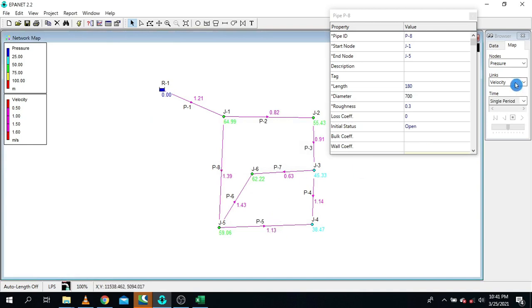At least now, okay, unit head losses, both of them are below 10 meter per kilometer. You can see here is 0.8, 0.7. Again, this one is 2, this is 3, 4, 10. Not bad. So at least now our system is well balanced. Velocity is within acceptable range, and again, unit head losses is within acceptable range.